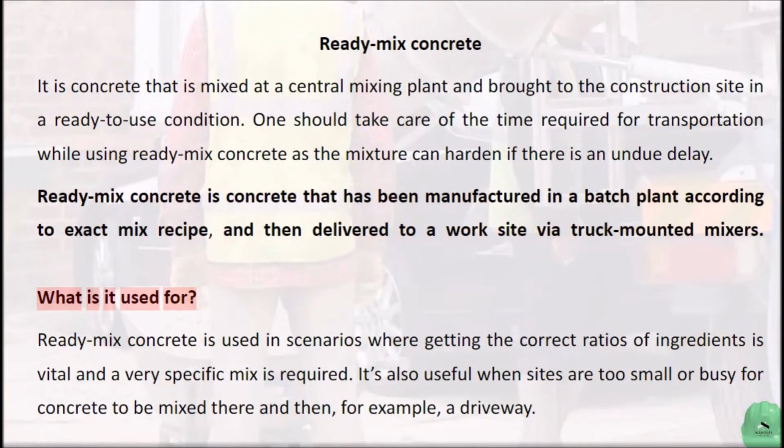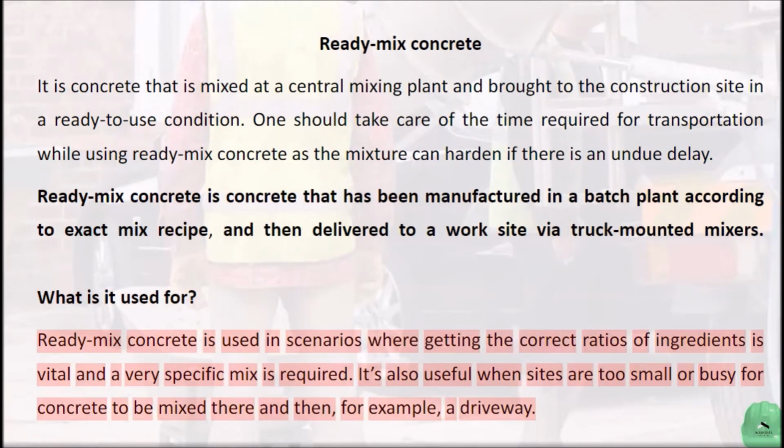What is it used for? Ready-mix concrete is used in scenarios where getting the correct ratios of ingredients is vital and a very specific mix is required. It's also useful when sites are too small or busy for concrete to be mixed there and then, for example, a driveway.